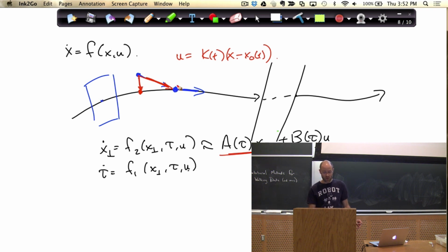In practice, the gains you get back in the full coordinates for the controllability of some trajectory can be very large. If you just try to stabilize the n-1 dimensional system, then you might get numerically much better conditioned systems, much lower gains. It can make a big difference. We've also seen places where it doesn't work well at all. If you try to stabilize the pendulum by stabilizing transverse coordinates, there are places where the trivial transverse coordinates are not controllable, even though the original system was controllable. You can get yourself into trouble.